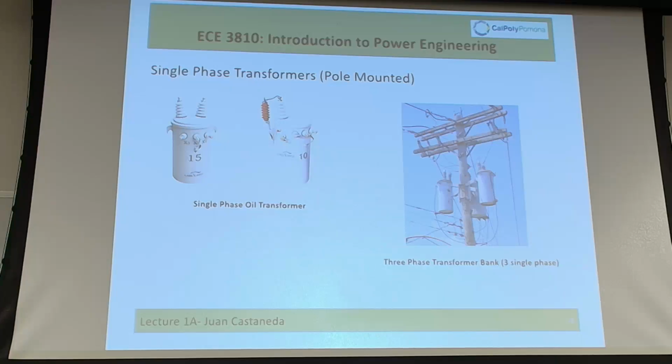Now, the other thing I was going to tell you, probably the most recent development in cooling for these small transformers, not for large ones, for small transformers, and you can Google that one too, is called FR3, a type of oil. It's an ester fluid, as we call it.